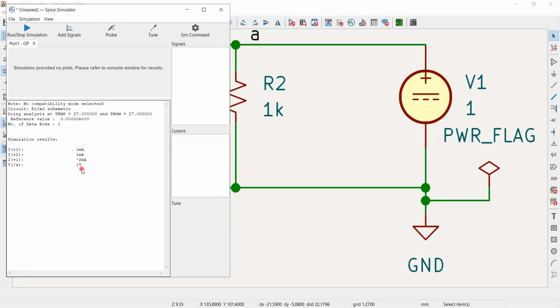So the total current is 2 milliampere basically. Because R1 and R2 are in parallel, their effective resistance is 0.5 K. So 1 divided by 0.5 K, that is Ohm's law, gives you 2 milliampere current, and then 1 milliampere in each resistance, as that current is divided. And the total current is 2 milliamp, and the total voltage across the nodes is 1 volt.